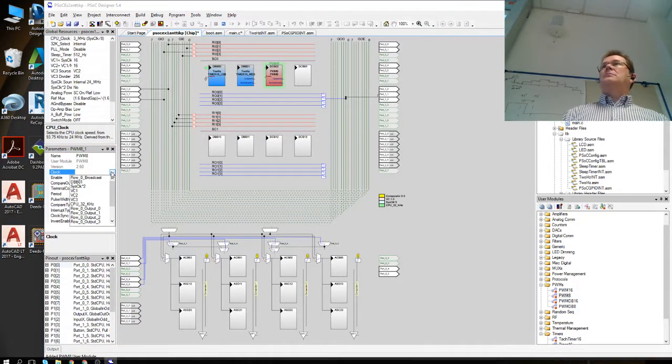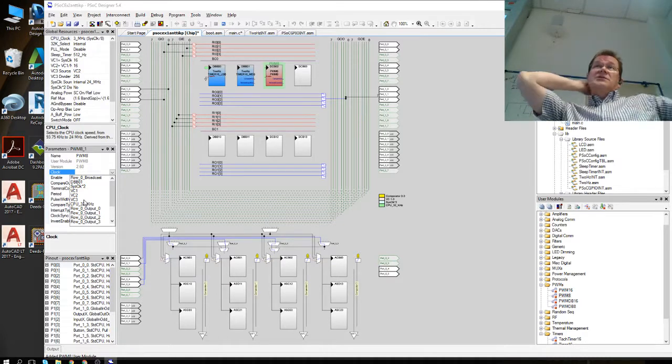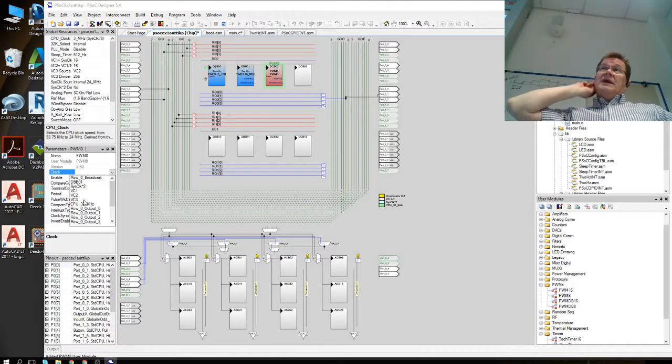Okay, which clock to use? Plenty of different sources. It could be VC3, but then you must do the division of those initial clocks accordingly. You can also use the 32K clock if that gives you enough resolution for your system.